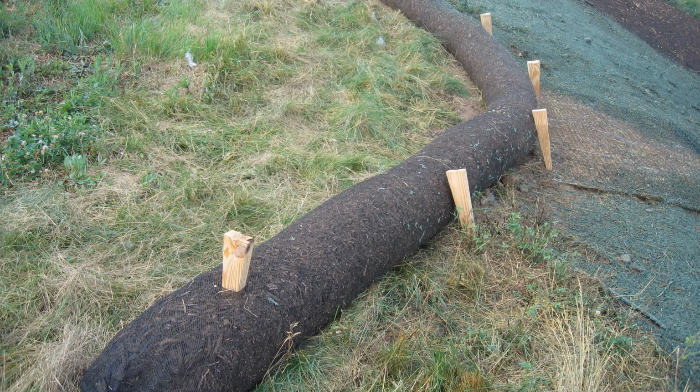Terraces and retaining walls catch runoff, giving water time to soak into the ground and make attractive planting beds. Structural controls should be sloped by about 2% perpendicular to a hill's decline to direct drainage to the sides and prevent pooling. Install perimeter control, such as silt fences, on all downgradient perimeters. Remember, structural controls and native vegetation only prevent erosion if they are well established and maintained.